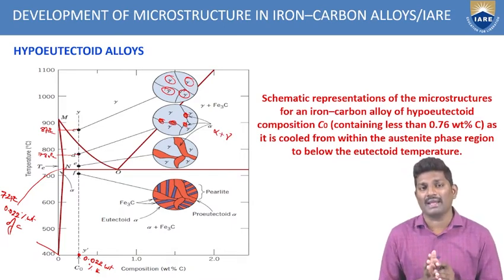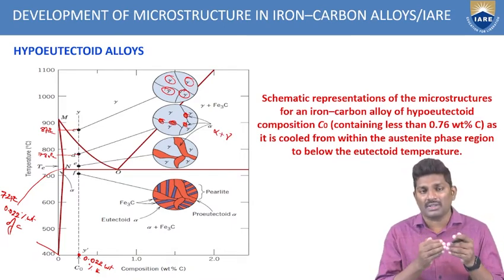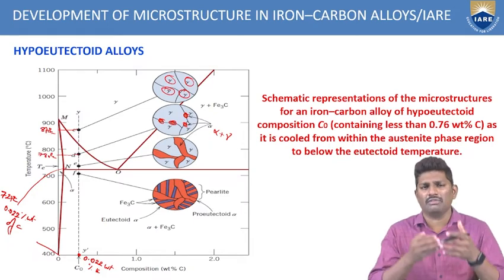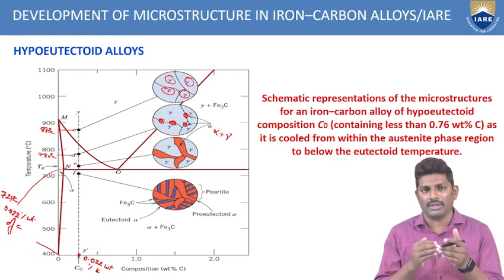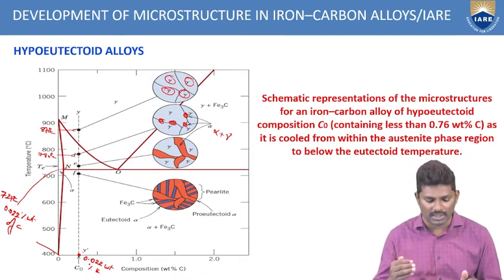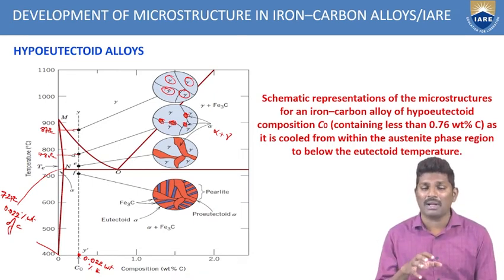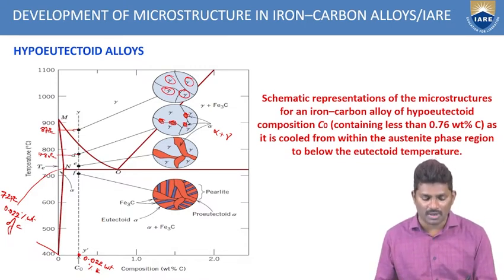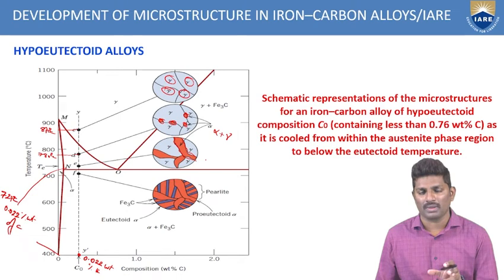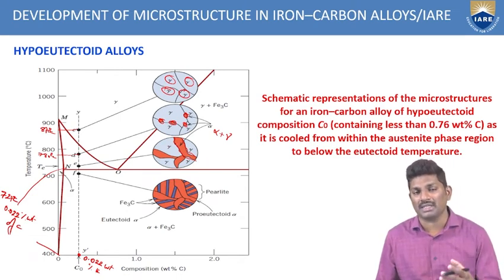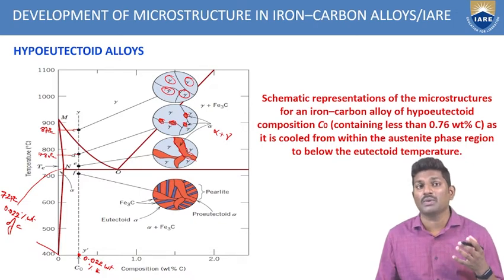So you have ferrite and austenite after reaching 870 degrees centigrade. Now if you reduce the temperature further, that means the system is being cooled. What is happening? There is an increase in the percentage of alpha particles, that is the ferrite particles. Slowly cooling the system, there is some increase in the area of the alpha zone. Of course, there is a gamma zone, that is the austenite zone, but the domination of alpha slowly increases as the system is cooled.